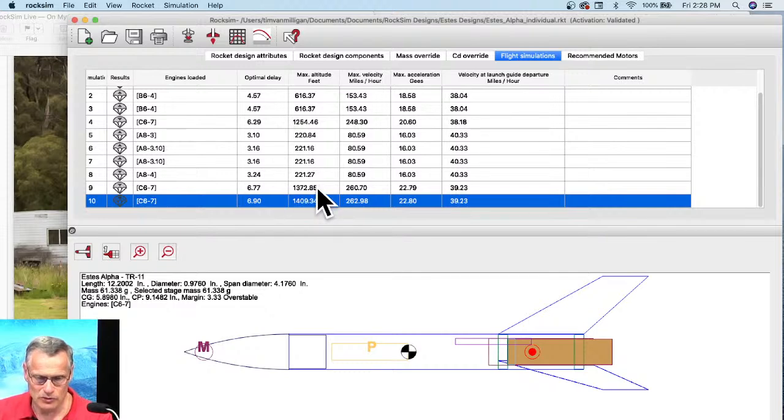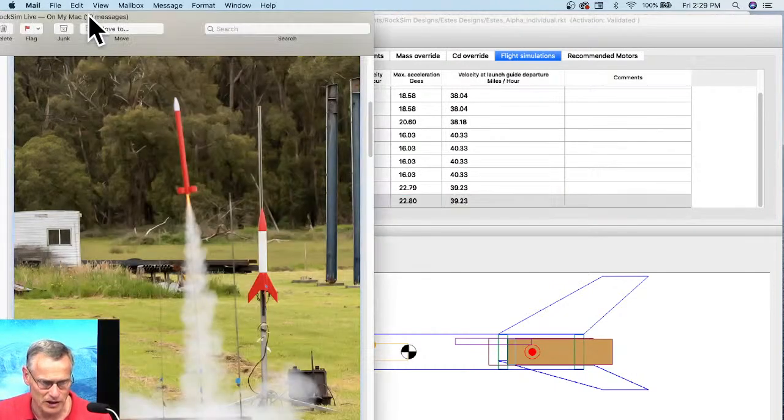So, as the temperature comes down, the density of the air increases because the air particles get closer together. And so you're trying to push your rocket through particles of air that are closer together, and so you get higher drag. And so that's why you'll see that temperature difference. So just change the temperature. See, that was a really easy one to do.